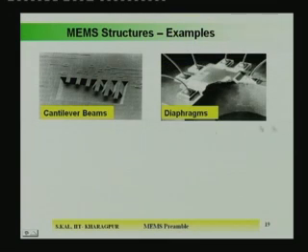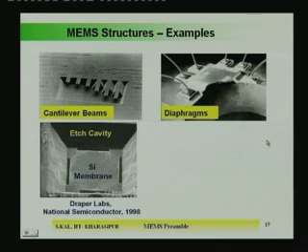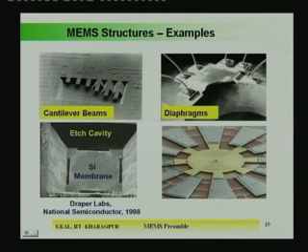On the other hand, here you can see this is a diaphragm. On the diaphragm some devices are made, and these are the bonding pads from where the wires are taken out, and these diaphragms are used for many vibrators. In some cases the diaphragm or the membrane is used in sensors like temperature sensors or IR detectors. Here is another structure, a silicon membrane at the bottom of the silicon, and this membrane is held by 4 cantilevers. This is one flexure, another flexure, and these flexures are positioned in such a fashion that the whole membrane is held properly. On the membrane you can make active devices, or some passive components, or you can use the membrane only for actuation.